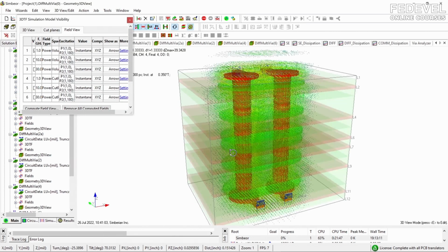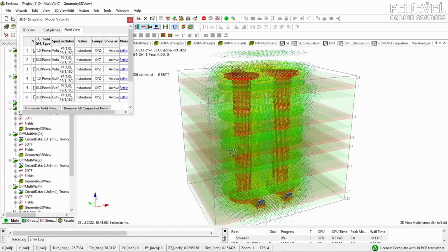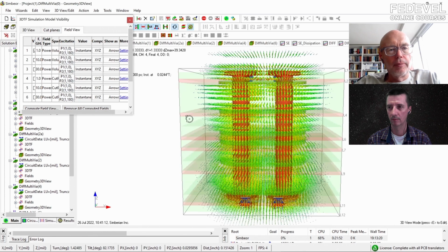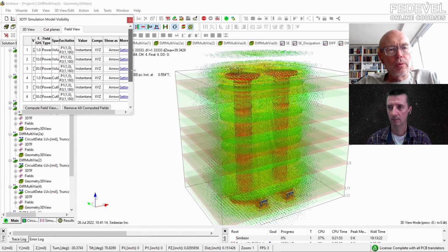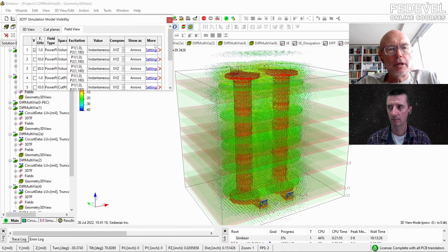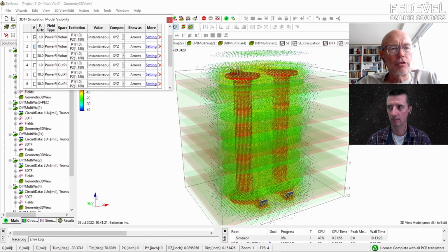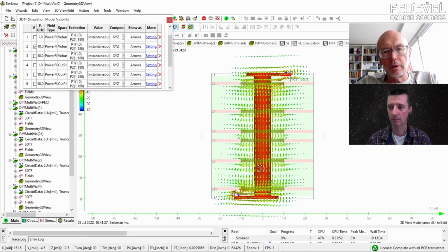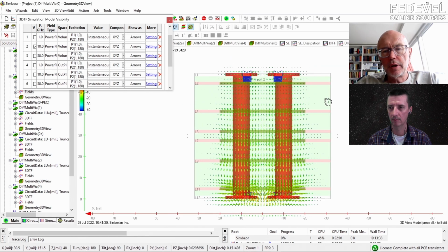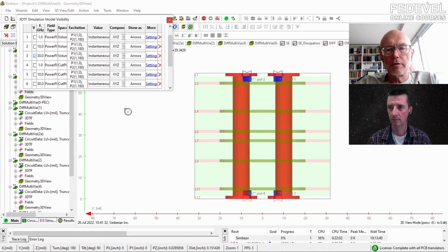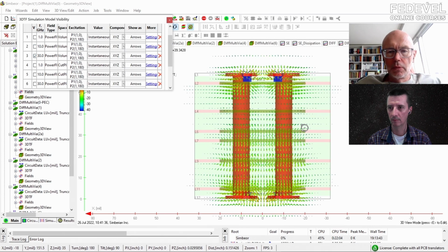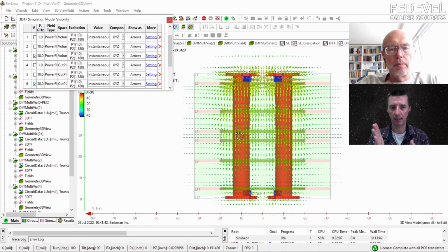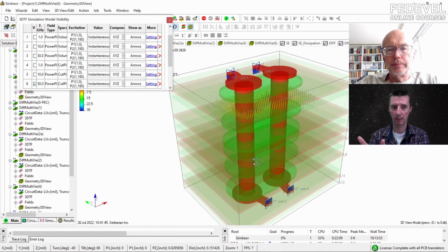You may think that by switching to differential, you may forget about stitching vias. Let me show you a simple example. That's what we are now looking at, the true differential, and presumably they should be fine without any stitching here. But if you take a look at 1 gigahertz and then at 10 gigahertz, you'll start seeing some energy disappearing mostly sideways, this way and this way. At 30 gigahertz, you can see more and more energy going sideways. This is basically exactly the same as single-ended with stitching vias. That's exactly what is also happening here.